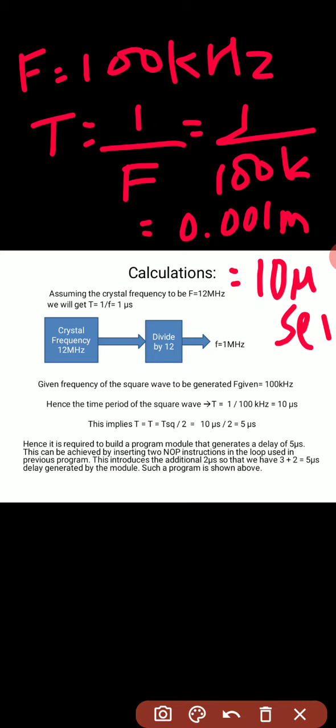So let us see how to get that, what value or how many machine cycles you need, and how to calculate that delay, right? So we know that, let us assume the microcontroller is working with the crystal frequency of 12 megahertz. Actually the 8051 or 89C51 that we discussed in theory was working at 11.0592 megahertz. So let us take the integer value for this frequency.